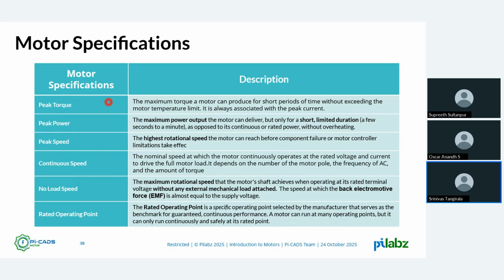So basically, as you have seen the EMF that Oscar talked about, the back EMF is because the motor also acts like a generator, in the sense it produces a voltage because the magnetic field is rotating, and you have an electromotive force because of the motion of the motor. It acts like a generator as well at the same time, right?